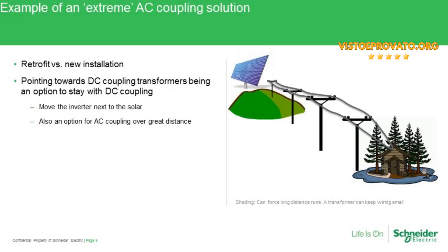The AC coupled portion with the XW Plus inverter, batteries, and just power distribution was all done down at the home. It was really nice to have an outdoor rated grid tie inverter up there, and then we just simply had a power shed down below that took all that power, stepped it down, and was usable inside the home. Really, really nice way to do this configuration.